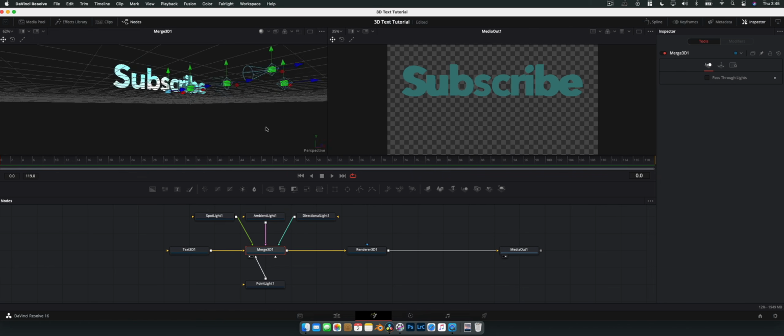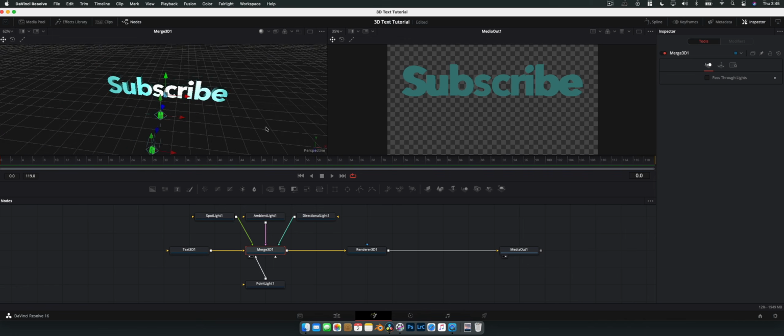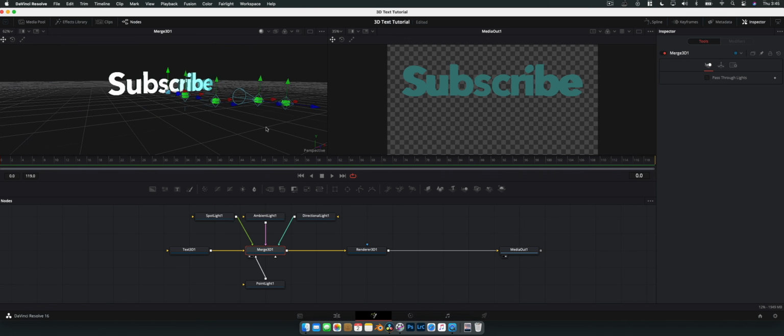We've got a lot of different lights, and we've got our text lighting up like the 4th of July. What you can see here is all our lights, and if we were to move some of them around, you can see on the text there, we're getting some light falloff. But we're not seeing anything in our Media Out node. And that is because by default in Fusion, inside DaVinci Resolve 16, lights do not automatically go through the renderer. We have to manually turn that on via the Merge 3D node. So you'll notice here with the Merge 3D node selected, if we go over to the inspector, the very first option is Pass Through Lights.